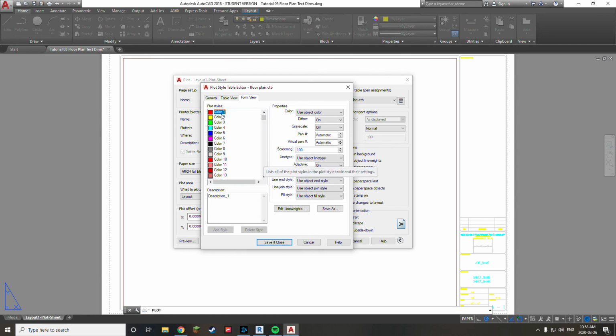I'm going to click on the very first color. I'm going to hold the shift button on the keyboard, scroll to the bottom, and choose the very last color, and then release the shift button. That way, when I make changes, it's really changing everything at once. And why I'm doing this is that now when I change the color here, so any color on the screen, noted in this section, will now print as a black line, whether it's PDF or drawing or on paper or otherwise. So every single color on the screen will print as a black line.